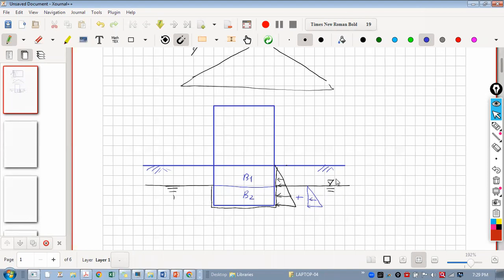We get that from the geotechnical reports, so that you can understand that I will take this height of the water for calculation of water pressure. Similarly, you need to calculate the uplift water pressure on the raft. And that's why you also require this data. So this H is important. The geotechnical people will give you this data: what is the height, or level, of the water below the ground?